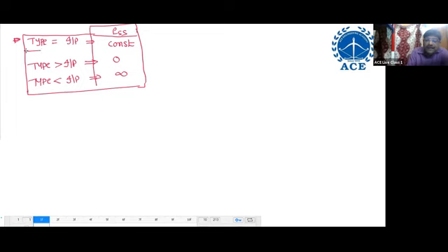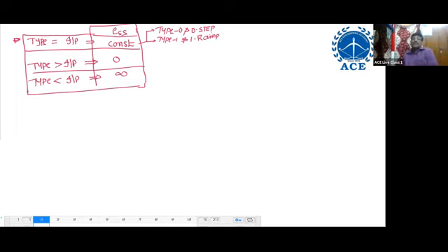So based on this, I make a conclusion that steady state error is required to be calculated for only 3 cases. Type 0 and 0 input, that is called step. Type 1, 1 input is ramp. Assign the value to the input: step is t power 0, ramp is t power 1. Next type 2, and the second input is parabolic. In all the remaining cases, the error may be 0 or infinity.